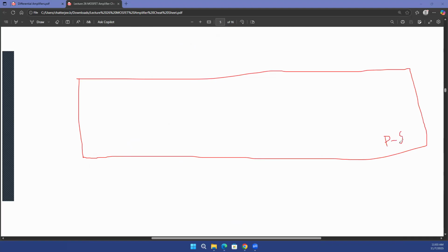Usually you get p-type semiconductor wafers in the market. So let's say you buy this p-type semiconductor to start designing your circuit. Generally, all the MOSFETs in the circuit are created on it. You create your NMOS over here. So you have N, and then you have a gate. You create another NMOS just beside it. Let's say N, and then you have a gate.